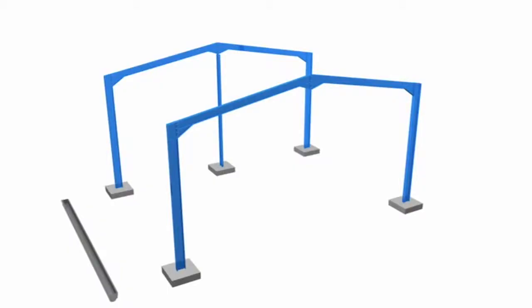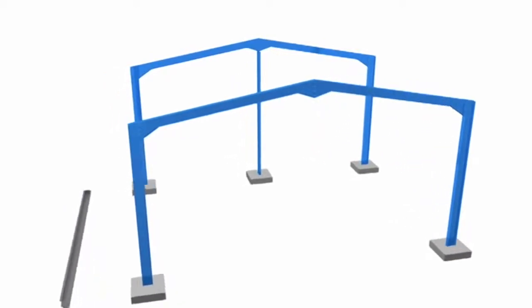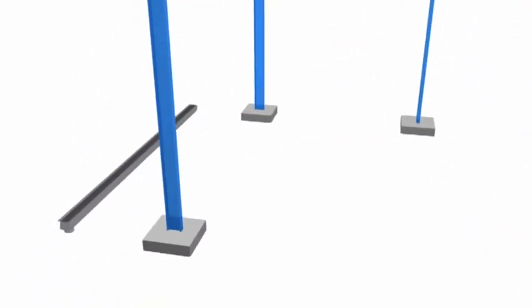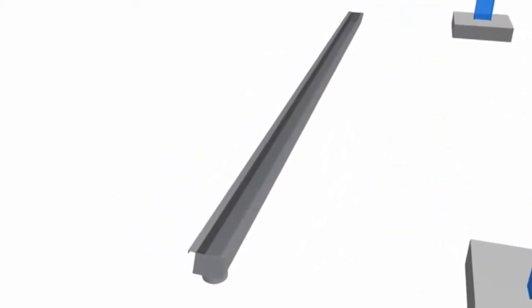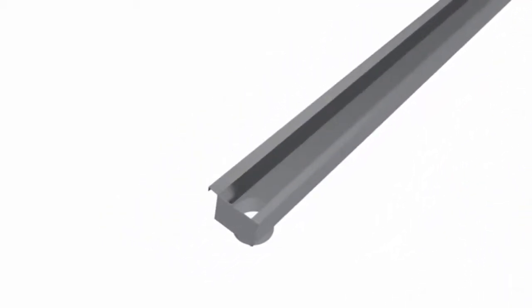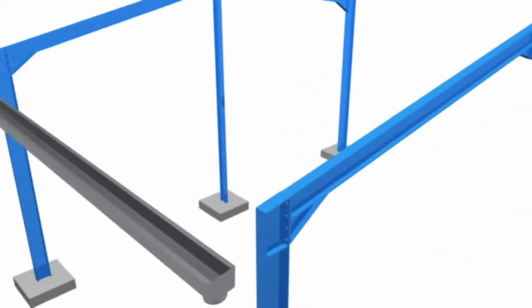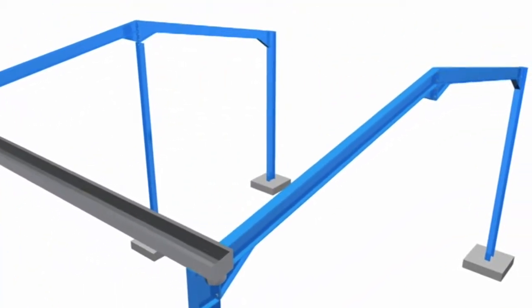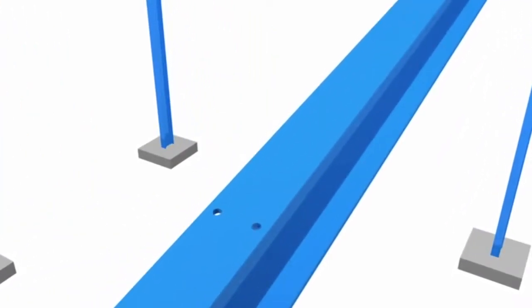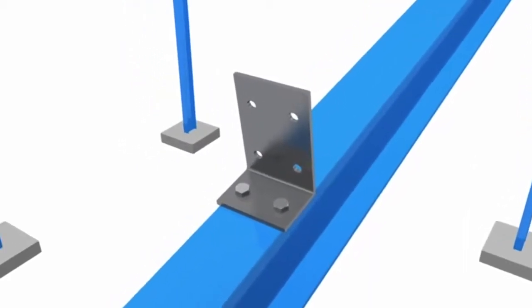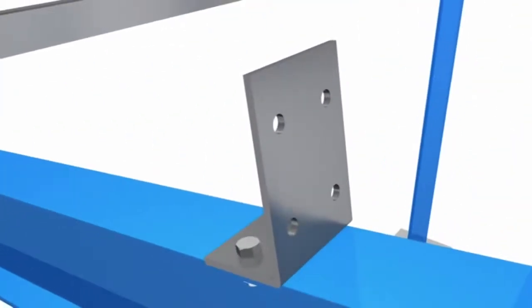For the columns of our shed, we determine the live and dead load forces placed upon the structure to determine the most suitable column. The first step we took was accumulating the data from the wind bracing, ceiling system weight, cladding material weight and the weight of the rafter. The column needs to be able to withstand the loads to transfer the weight into the footing. Once we collected the load weights, we calculated the total dead load of 52.208 kilonewtons.